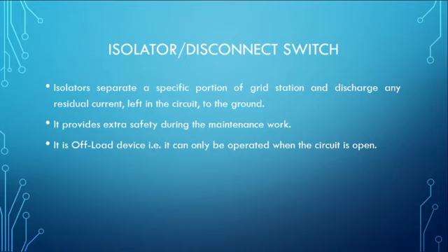There is no quenching medium in an isolator, and hence it cannot extinguish the arc which is produced by operating an energized circuit. Therefore, before opening isolator, first you must open the concerned circuit breaker.